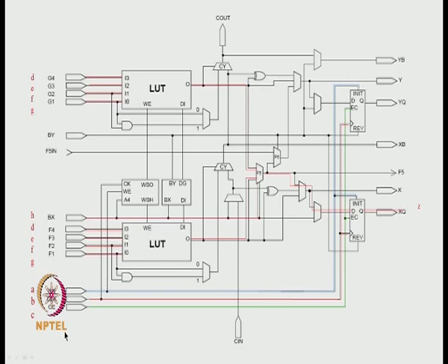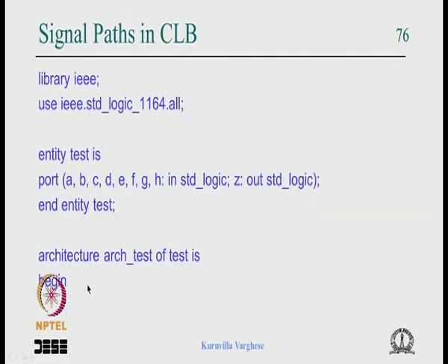As I said, you can write this code, select a Virtex FPGA or a Spartan 3 FPGA and synthesize it, implement it, go to the floor planner, open up, then you can zoom into the CLB which is implementing it, and then you can see this wiring connection inside there. So you can verify that it's working. If time permits, I will show this exercise in the tool.